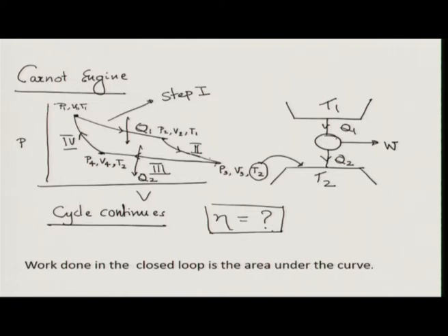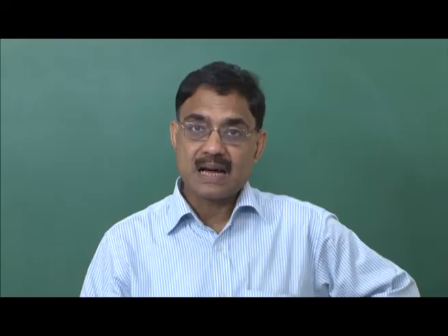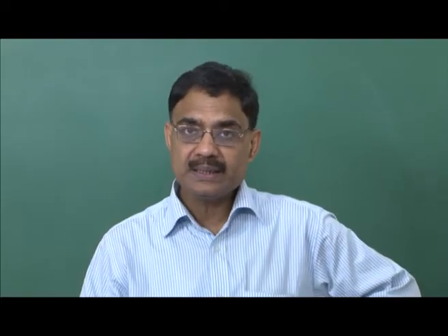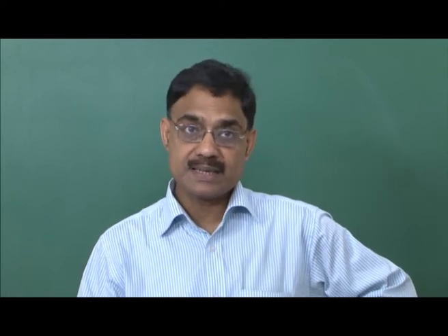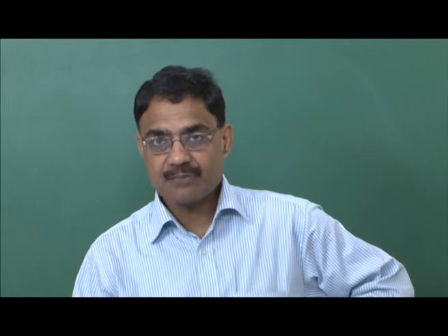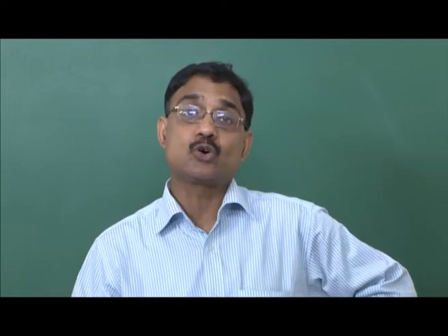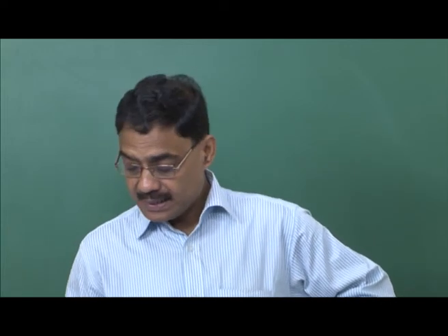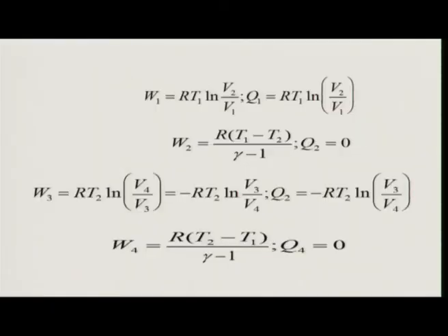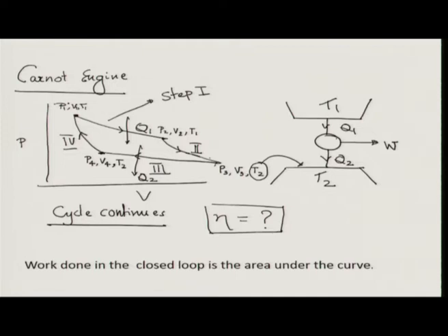To calculate the efficiency of this Carnot engine, I have to calculate the work done and the heat absorbed or released in every process. In the case of work done also, we have to be careful whether work done is on the system or by the system. By the system is positive, on the system is negative. Let us proceed. So, first step, step 1. This is the step 1.